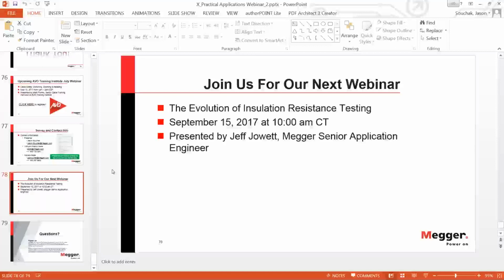So if you had a fully grown water tree, which I think Jason was referring to, one of those water trees that has almost crushed the entire insulation, it just takes one voltage spike and the cable will blow. So the tan delta will not show you that one spot, okay? So it's always a good practice to do that.